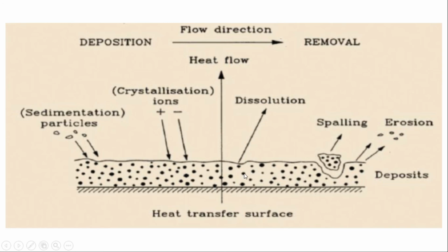So the higher the thickness of the fouling layer, the more additional resistance there will be in the direction of the heat transfer. That's why the fouling should be at a minimum in order to maximize the heat transfer rate.